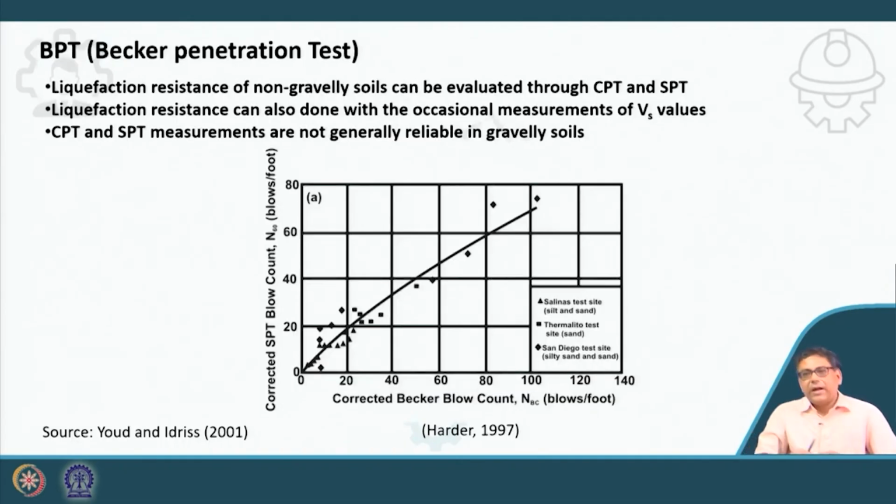So now, as I mentioned, sometimes if your generated pore water pressure is not allowed to dissipate fully under the condition, then some gravelly soil can also be liquefied. But the liquefaction resistance of non-gravelly soil can be evaluated through CPT, SPT.